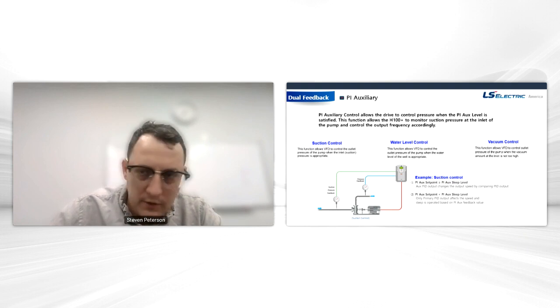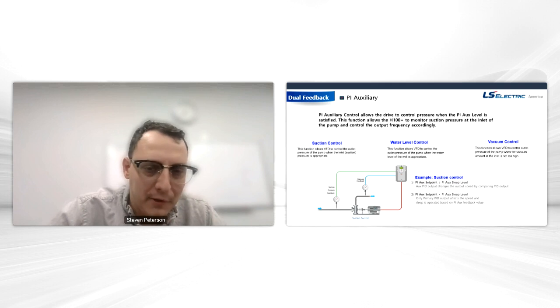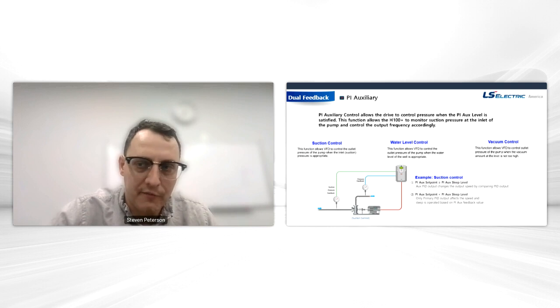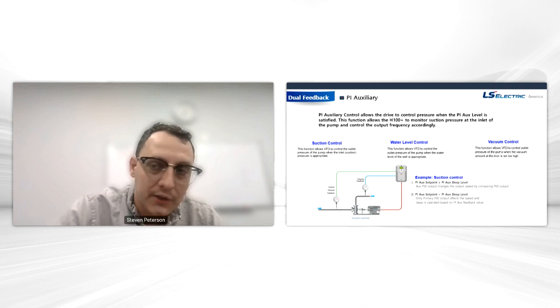All right. Hopefully you guys found that video useful. I tried to demonstrate all the functions in a short amount of time, at least the key functions. And one of the big things is the redundancy: if one drive's running and it shuts down, whether it's a trip or somebody shuts off a disconnect, the secondary drive, which might not be running at the time, sees that, and then it kicks on.